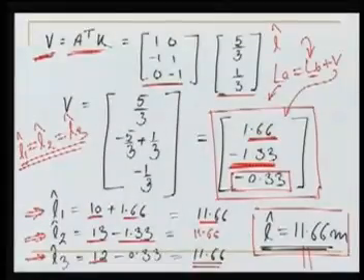We have now found the desired thing. The desired thing was the length of the line. Okay, the estimate of the length of the line, which we have found as 11.66 by following the procedure, so that we included all the observations and followed the condition equation method and adjusted the observations.